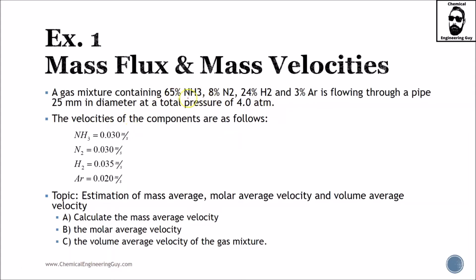Okay, first things first, we are not given any kind of value of the percentage. So you could be talking about mass value, molar value, or volumetric values. Since we are talking about gases, I'm going to assume that this is molar value, even though it's not for sure, but let's say for the sake of this example that this is true. And it's flowing at a diameter of 25 millimeters. So I'm going to assume that this is the internal diameter at the given pressure.